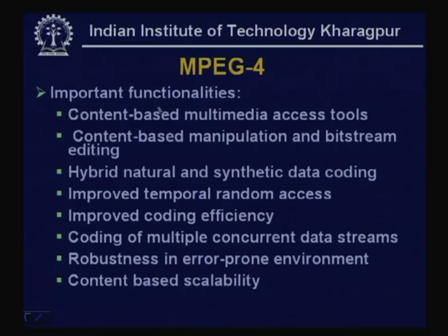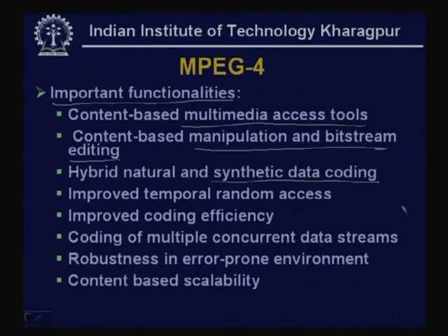We have seen in MPEG-1 and MPEG-2 essentially the techniques are concerned with compression, but apart from compression, MPEG-4 has got many important functionalities: content based multimedia access tools, content based manipulation and bitstream editing, hybrid natural and synthetic data coding, improved temporal random access, improved coding efficiency, coding of multiple concurrent data streams, robustness in error prone environment, and content based scalability.